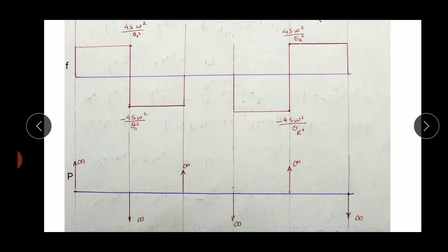So the slope of the acceleration graph is jerk and it is a vertical line. That's why we need an infinite amount of jerk in the negative direction to go from a constant amount of acceleration to a constant amount of retardation. That's why we have to plot it like this. So practically we need an infinite amount of jerk to achieve this.